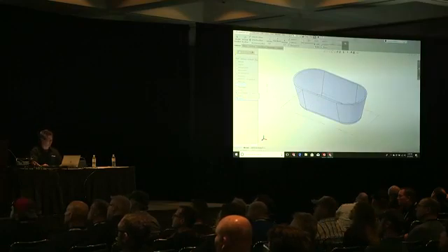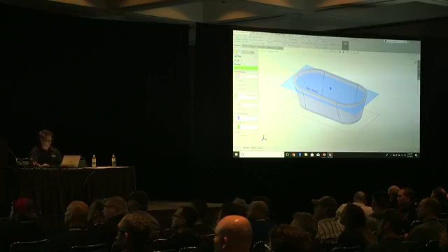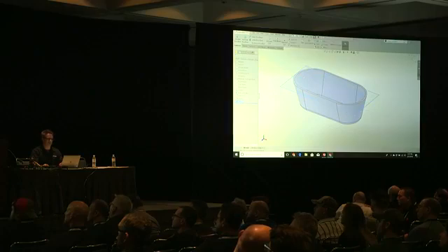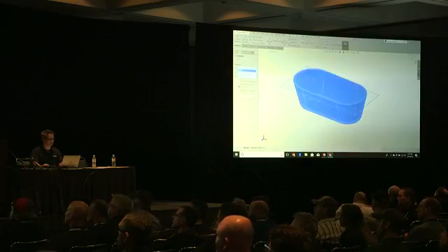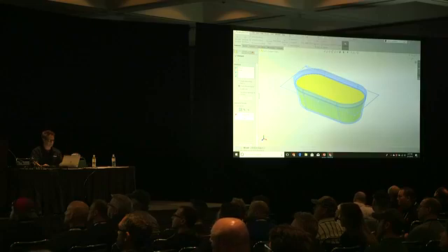Top plane, if you remember, control, drag, make a copy. Say OK. I'm going to use this as my water line. Use intersect, hit that. Create an internal region. You can do create both. You could do either or. I'm creating the internal region.